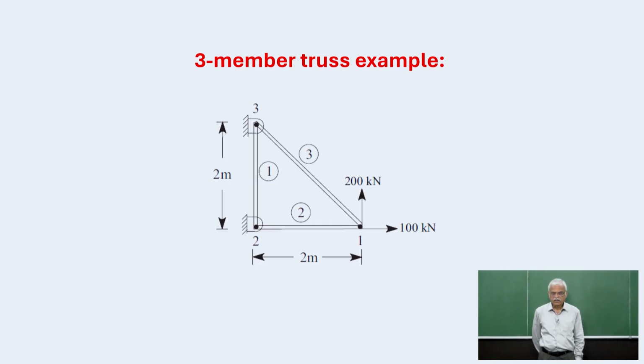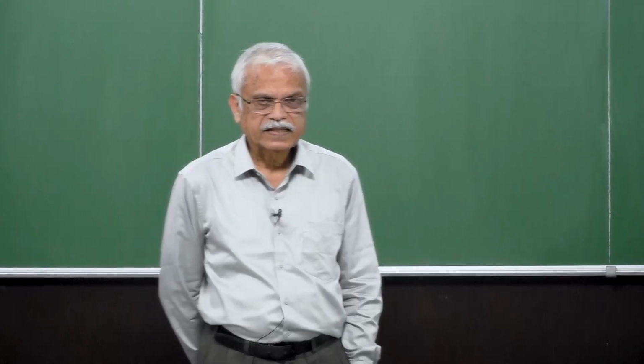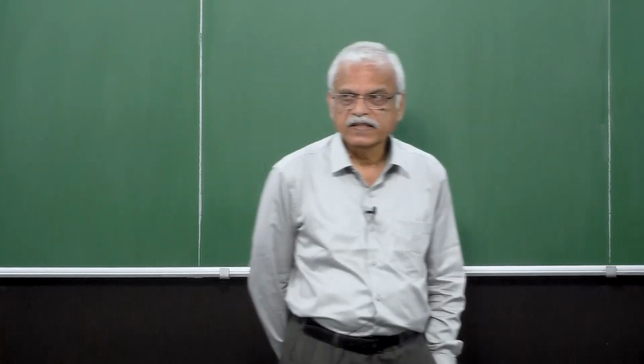degrees of freedom. And in the last class, we talked about the 4x4 stiffness matrix for an element at a general orientation alpha. So by changing the alpha here, we can get the equilibrium equations or the stiffness equation for each element.